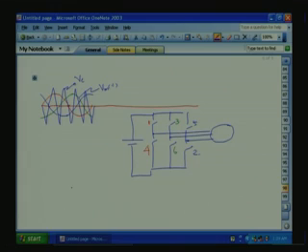When the A phase sine is greater than the triangle, the top is on. Sine less than the triangle, the bottom switch is on. So, this independently we carry out for the 3 phases A, B, C.